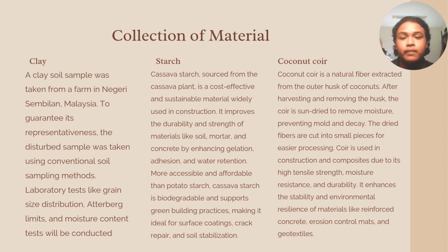Collection of material. First material is clay. A clay soil sample was taken from a farm in Negeri Sembilan, Malaysia. To guarantee its representativeness, the sample was taken using a conventional soil sampling method. Laboratory tests like grain size distribution, Atterberg limits, and moisture content tests will be conducted.